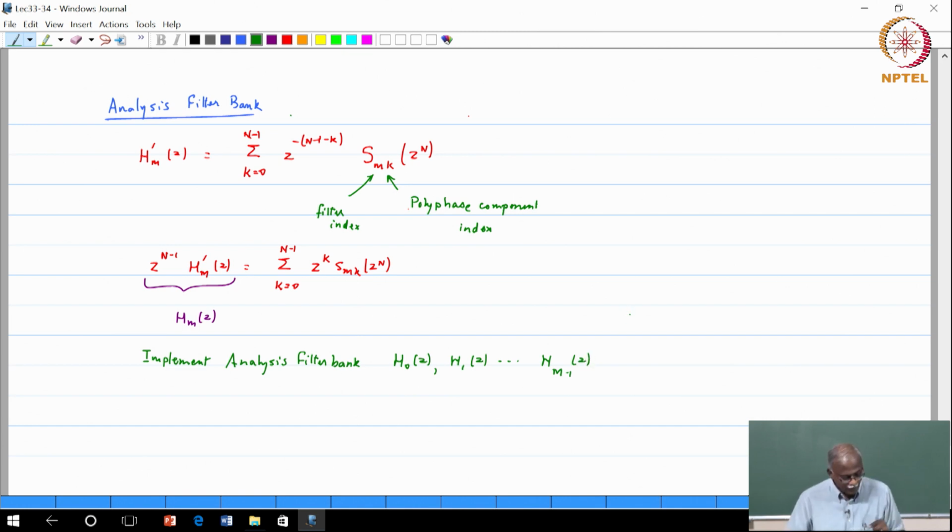Okay. Now, remember this is a type 2 polyphase decomposition, and I want to characterize this. So here is the polyphase implementation that we will achieve with this, and basically now we would then put the two pieces together to get the complete multi-carrier system.